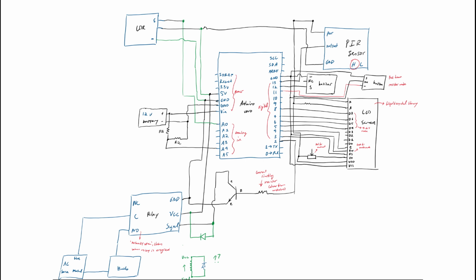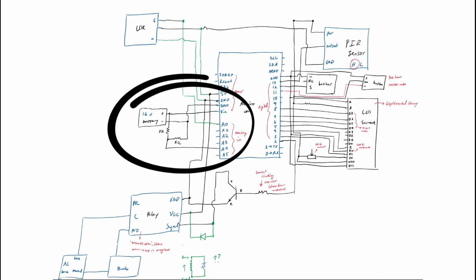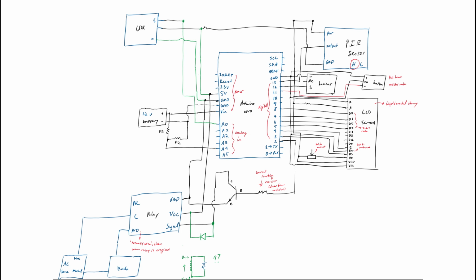As you can see here, to measure my battery charge level, a simple voltage divider for my battery was used. That way I could send a safe, low voltage corresponding to my battery voltage level to my analog input pins, which could then be translated to the real battery voltage via voltage divider rule. On the right side of my Arduino, I have my LCD screen interfacing with my digital pins in 4-bit mode, as well as my other sensors which are powered and grounded.